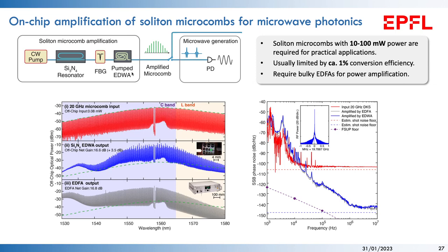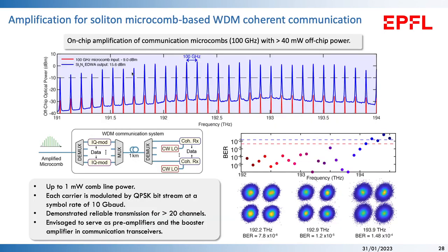This is simply because of the regenerative amplification, or the amplification enhancement at particular wavelengths, because of the FP cavity of this chip. But compared to the case without optical amplification, the phase noise of the generated microwave at high frequency is limited by the photodetector shot noise. If you have the amplification, we can achieve a similar phase noise performance compared to the case using a fiber amplifier, which means our platform does not introduce too much impairment in this amplification process.